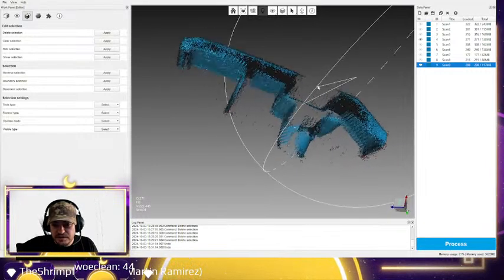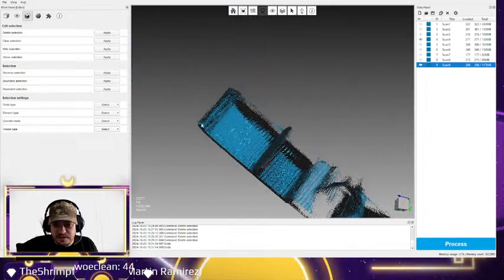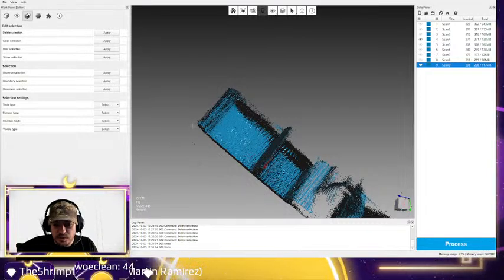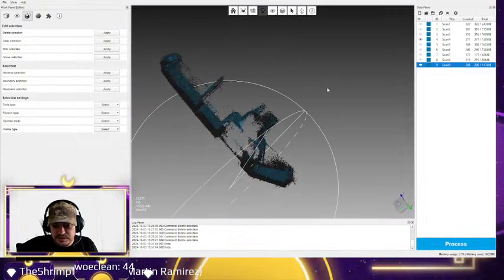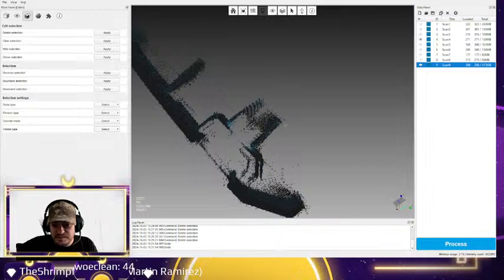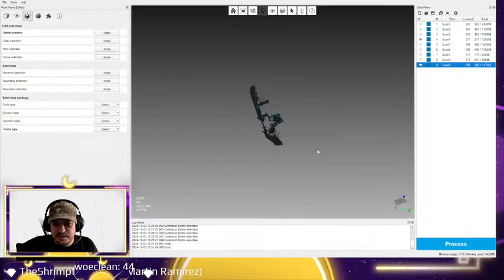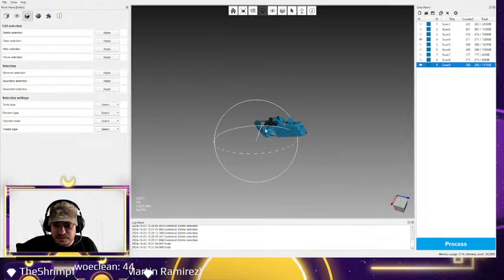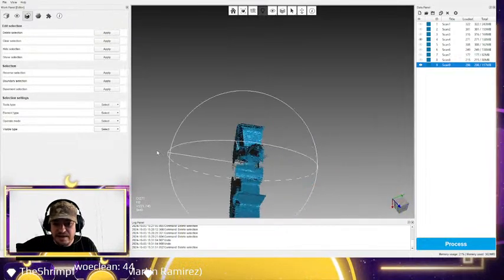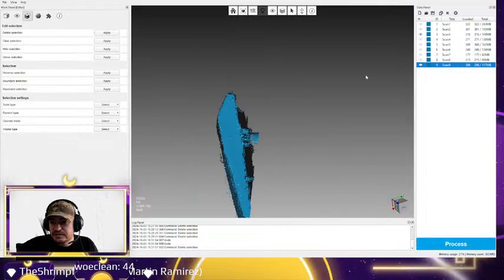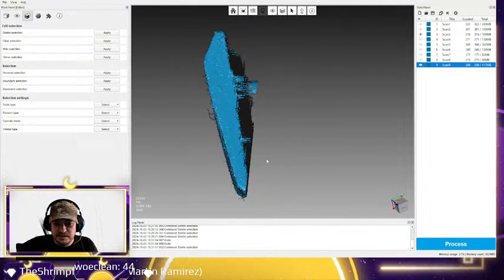Depending on the size of the object, how thick it is and how long it's taking to print, all that factors into how much it's going to warp from the build plate. And his objects are kind of big, so unfortunately, out of the multiple times that I've tried to print them, they just keep coming out oddly shaped. I did let him know that maybe an SLS printer would be better for him, the printers that use powder, but unfortunately that's not something that I have at my disposal. So he might need to reach out to actual manufacturers overseas to get his prototyping done in nylon.